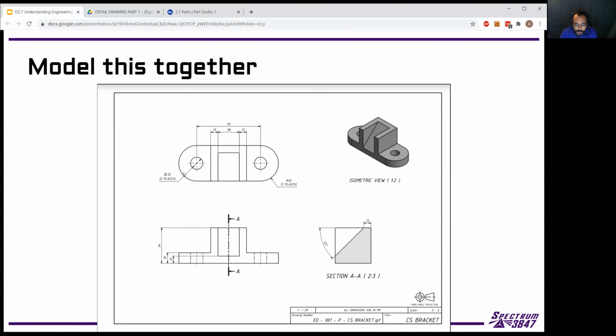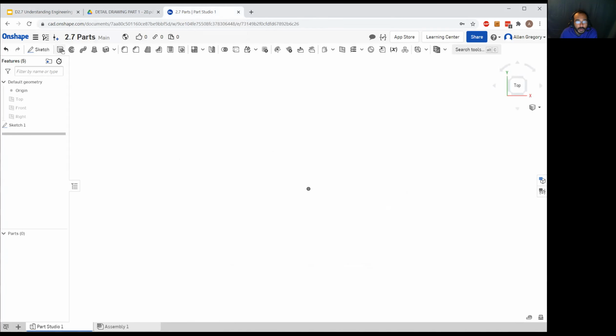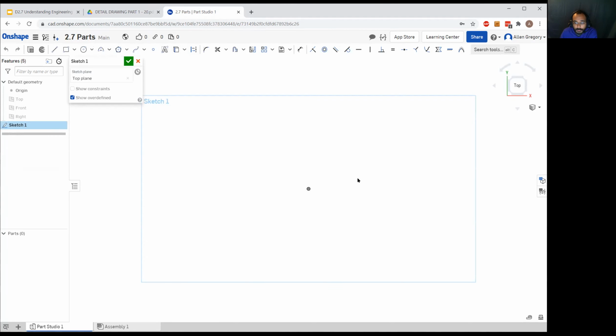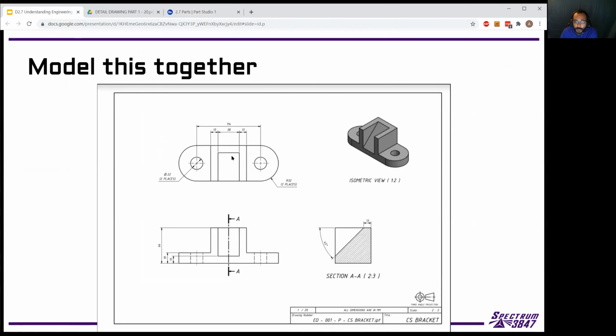Okay, so we're going to draw a portion of this top view first to get us started. So we're in this sketch now. There's a few different ways we could do this if we wanted to. The simplest way here is probably to draw a center point rectangle. So we can put the center of this part at our origin. And then we're going to look at figuring out some of our dimensions.